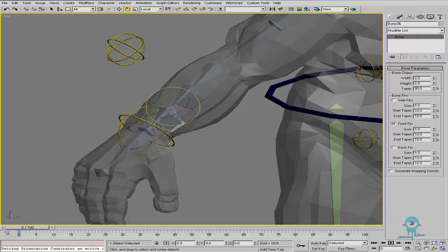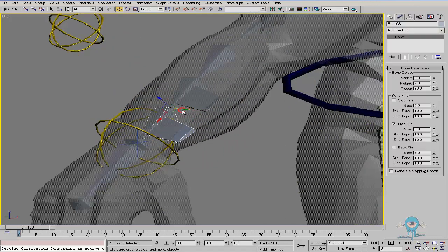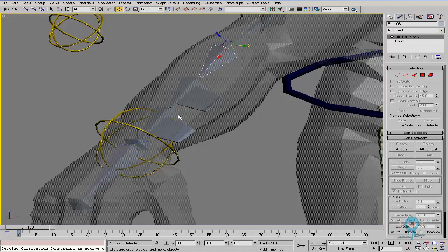The general rule is that the middle axis of the three, x, y, z, is the one that will flip at 90. The other two will flip at 180. So if we take a look at the local axis of this joint, y is across because that's how we originally had set it up.